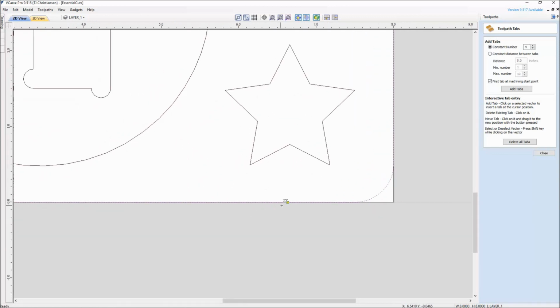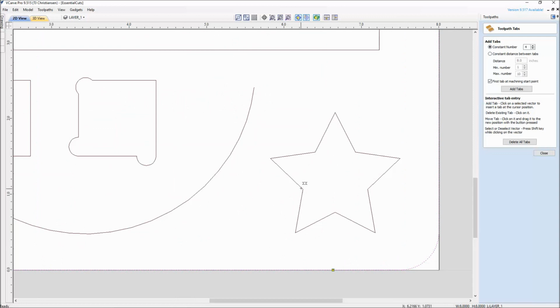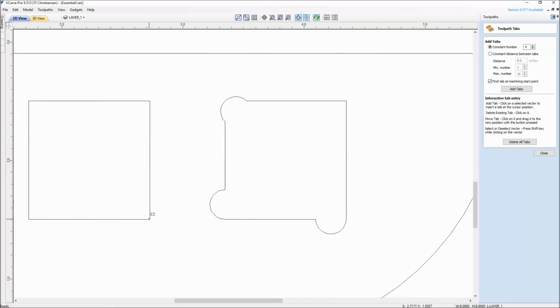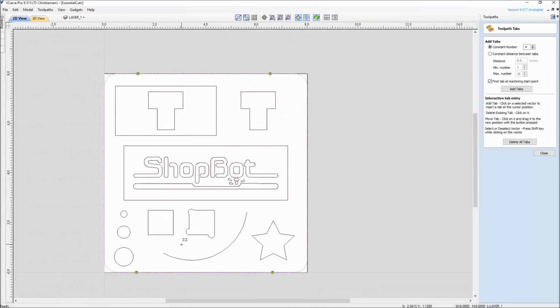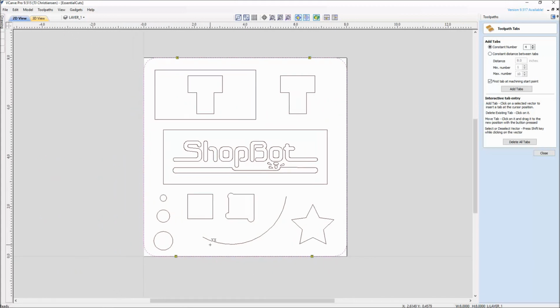And you could rebut that by saying the same thing about a straight line, but I'm talking about more intricate parts like this. If you were to have a tab down inside of a star or inside of one of these dog bones, or right here on the end of a corner, you're never going to sand that the same. So all I'm trying to point out is tab placement. Put them in a way that either gives your cut strength or keeps it from having lots of work to do when you clean it up at the end.